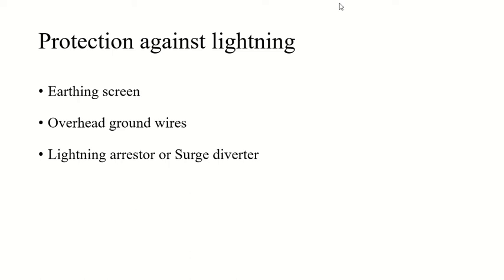So either by a direct stroke on the equipment, or a stroke on the transmission line, or a stroke on the transformer, a stroke on any kind of equipment reaches the equipment as a traveling wave. So it is important to provide protection against both kinds of surges, direct and indirect.